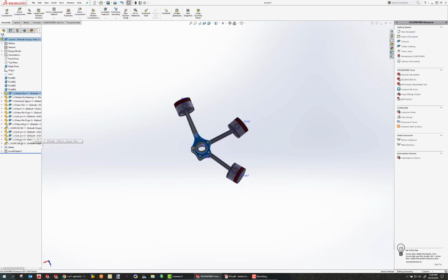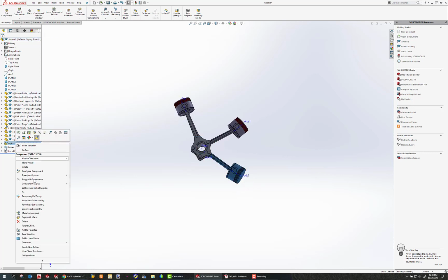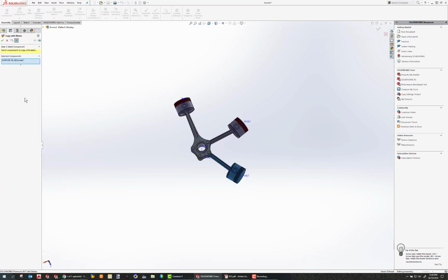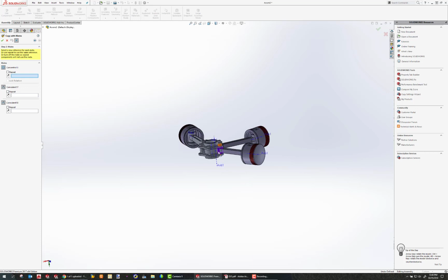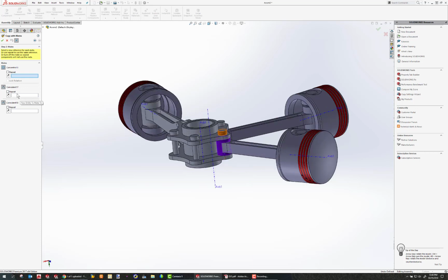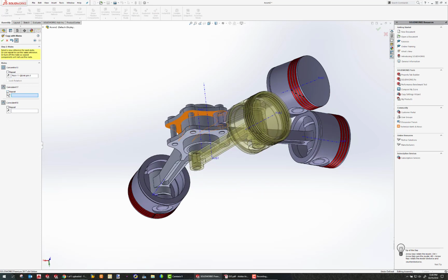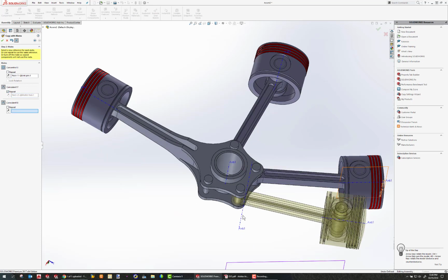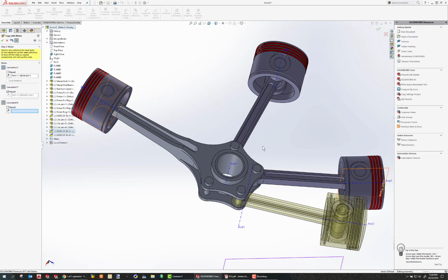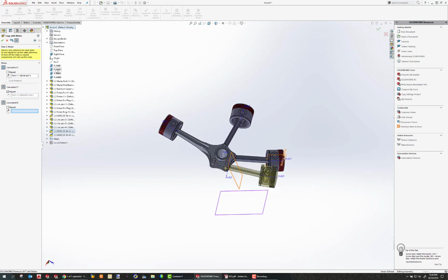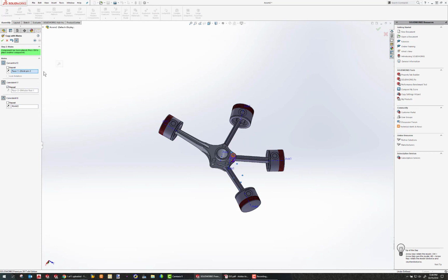Everything's looking good. Okay, let's take this exercise 5B and do it again. Copy with mates. Click the next. So I want to repeat the coincident. If I go into this, the concentric, let's select right there. The coincident, let's repeat. And now the planar mate, I have to find the correct plane that I created, which would be plane 2 now. There we go.